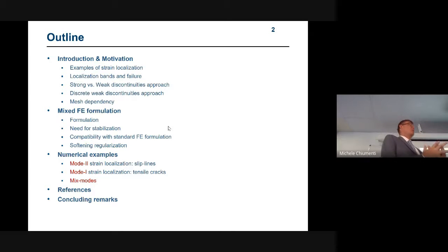Because all the deformation comes from the deviatoric part of the strains, and this means that the deformation in plasticity is because of the change of the shape and not the change of the volume. And if your solution is almost isochoric, like in plasticity, typically you have a locking of the solution. This means that if you use classical standard displacement-based elements, you can get locking. I will show you the examples. And pressure oscillation also.